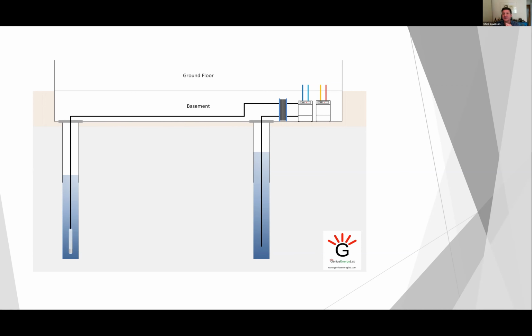Water then falls in from the surrounding ground into the well. The opposite happens in the recharge well. So we're actually using the weight of the water to push that water back into the ground. And you don't have to be an expert in hydraulics to recognize that if you've got water being pushed into the ground here and drawn out of the ground here, it's very likely that that water is going to migrate between these two wells. And I'll touch on that because it's a very important concept in working out how far apart these water wells need to be.